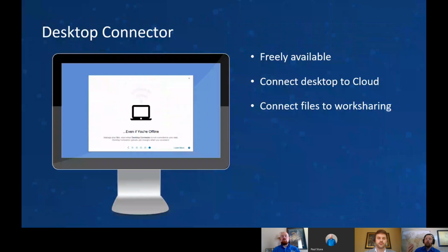Now, we can utilize document management with the desktop connector to just store models within BIM 360. In that sense, one person can still get in, access that model, do all their updates as they need to, and just push it back up as they're done. And then someone else, if they needed to, could access that model. Now that is a kind of disconnected workflow, but it is there. It is a very, very nice and useful workflow, especially with everything going on.